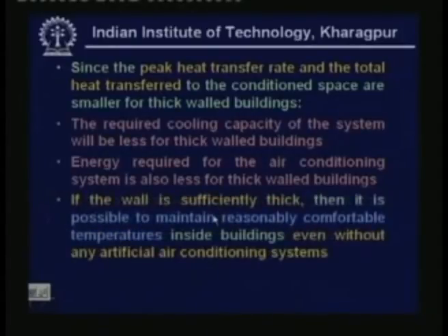And you will find that if the wall is sufficiently thick, then it is possible to maintain reasonably comfortable temperatures inside buildings even without any artificial air conditioning systems, because of the small decrement factor and large time lag. In fact, this is the principle behind the old temples and old forts or old buildings which have very thick walls. You find that these buildings even without any air conditioning are very comfortable even during peak summer. So this is because of the large thermal capacity of the building, which introduces small decrement factor and a large time lag.